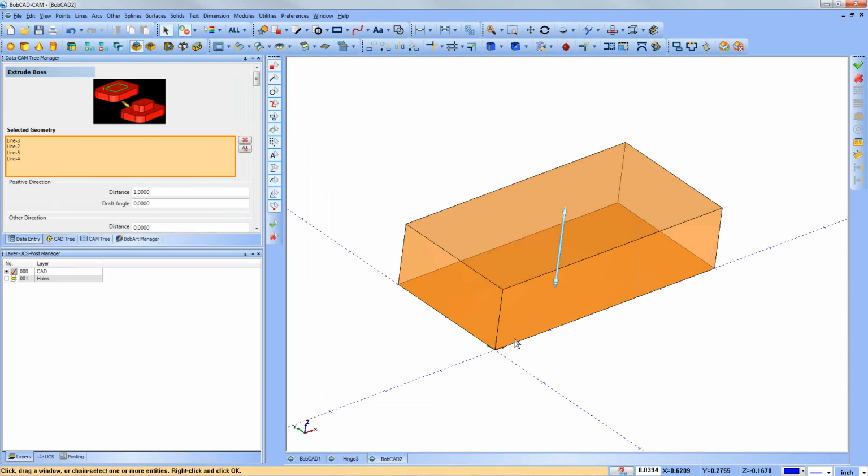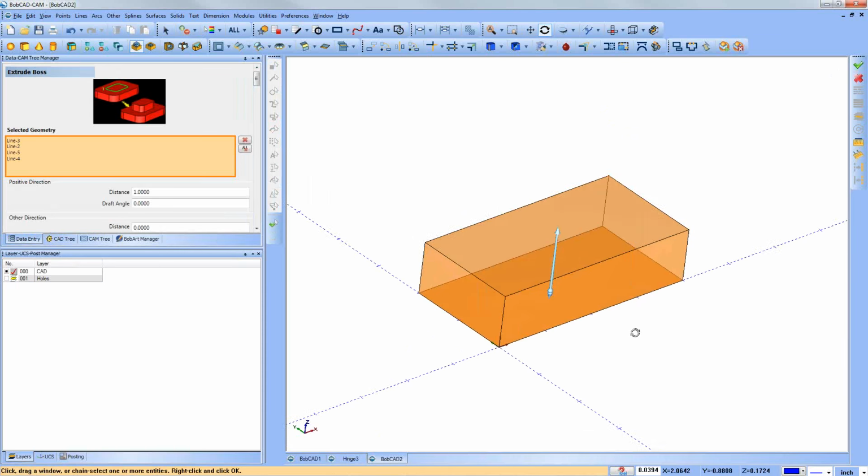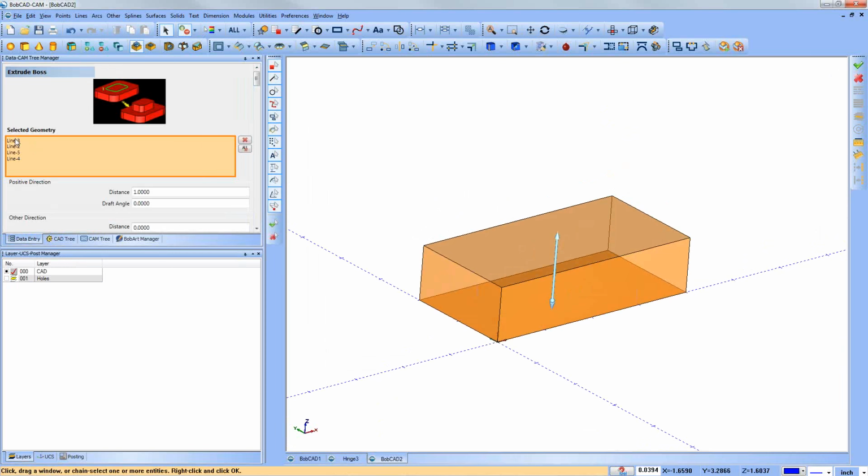This does a couple things. This will ensure that you have a closed chain. It does consider the chain selection tolerance that we have in preferences. We can talk about that a little bit later. But it will select that chain on that plane. In this case, I have this part selected, and it gives me a list of the geometry here. If I pick this geometry, it'll highlight which entity this is.